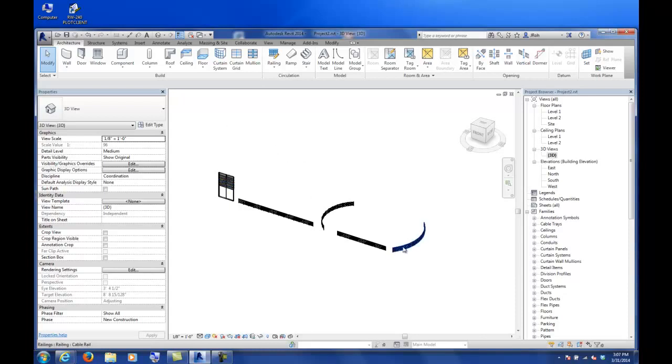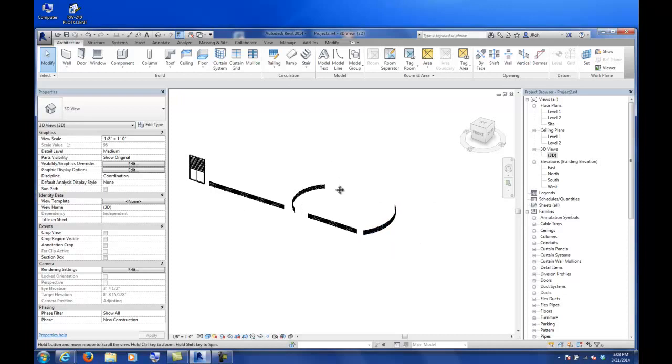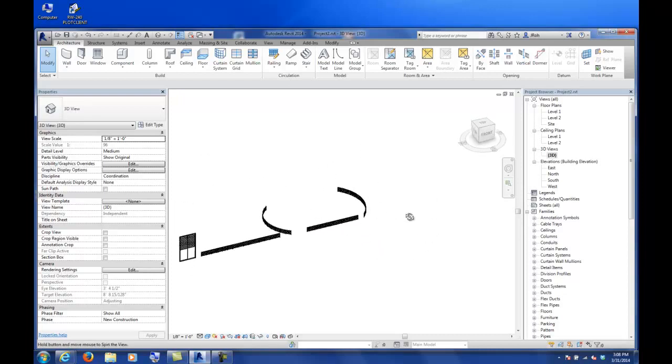and working with that tool, because the railing tool is going to be a host component to ramps and stairs. Rails are meant to not only be flat, but once they're hosted to an inclined surface, they'll model an incline directly to the host, which is nice instead of having to model those all the time.